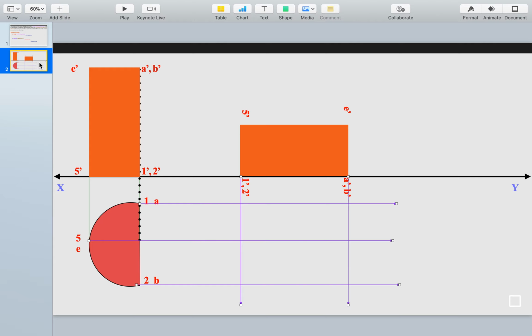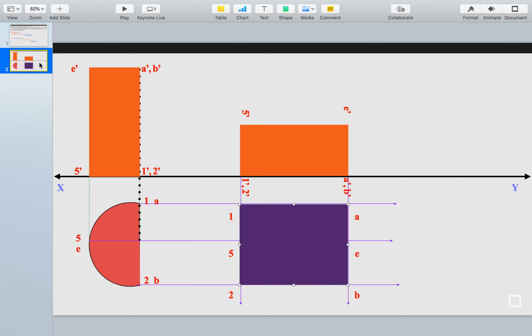After transferring the projection, draw the top view in the second stage. So we have drawn the top view in the second stage. In this way we have completed the second stage, but if you draw only up to here, you are going to get hardly 1 or 2 marks, because we have still not drawn the section line. As I have already explained, it is 20 mm away from any face, and I have considered it as the top face. So the point I have located is 20 mm from the top face.